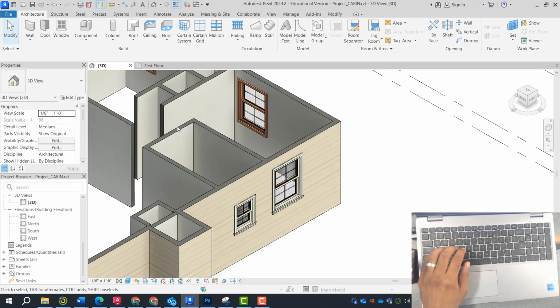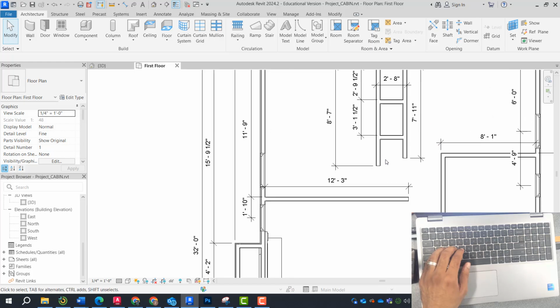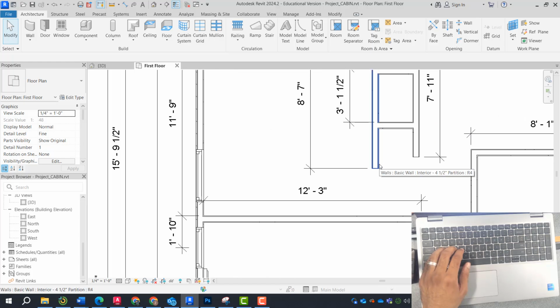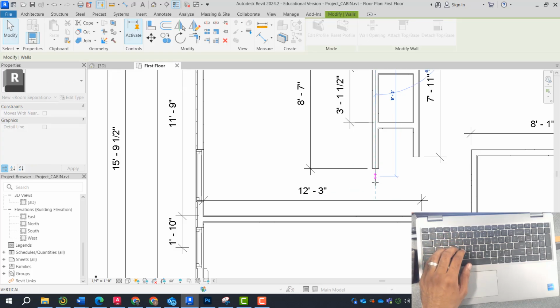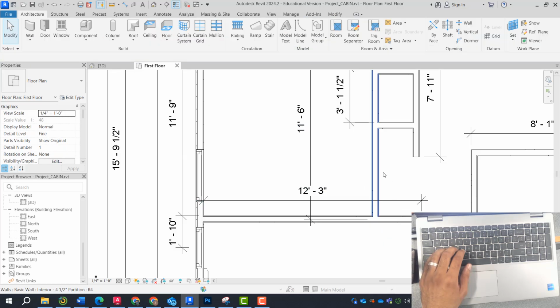Now something that is weird about going from AutoCAD to Revit is whenever you draw walls, especially in AutoCAD, you hesitate to draw them all the way through because that's where the doors are going to go. Unlike AutoCAD, we can actually take the walls straight through. Because when we place a door in, it acts like a host object and it cuts out the opening for you.